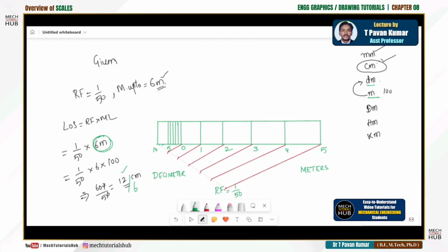Okay. And if one more point is given in the question, mark a distance of 4.2 meters. Finally, once you construct, do this and mark a distance of 2.5 meters. Now how do you mark it? I'll take a light color. As I said, for 4.2, one dimension leg on 2 and a dimension line followed by an arrow. For the previous problem I didn't make this. Now whatever number is asked, which is 4.2 meters, means 4 meters and 0.2 decimeters, means this subdivision will read decimeters, main divisions will read meters, and whatever the representative fraction given, that has to be written in the middle.